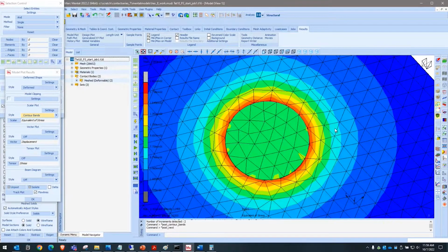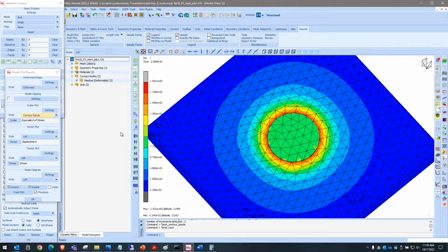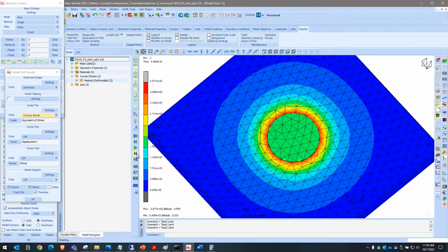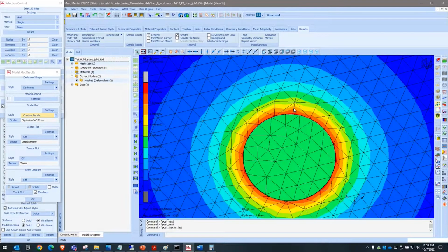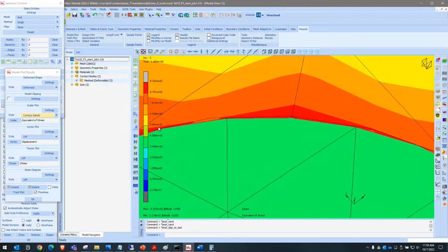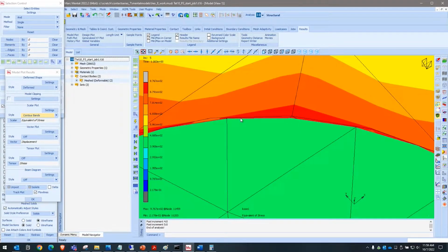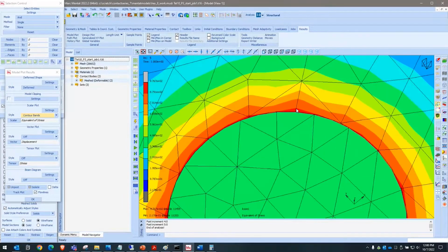Equivalent stress, and there you can see, let's say 200 MPa more or less for a 10 micron. Then as it runs 20, 30, now the pattern doesn't change, but the numbers do, simply because that gap is increasing. Okay, you'll also see if I zoom in, look at the deformed shape. So that's where that gap is physically opening up. There's a 20, sorry, at the end of this, there's a 50 micron gap. It's just not that clear with second order elements.